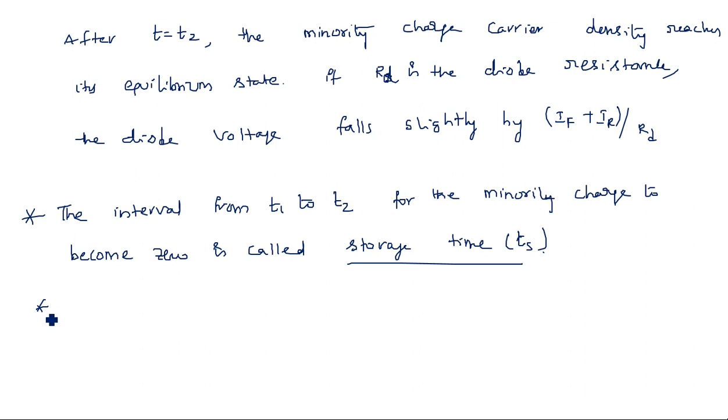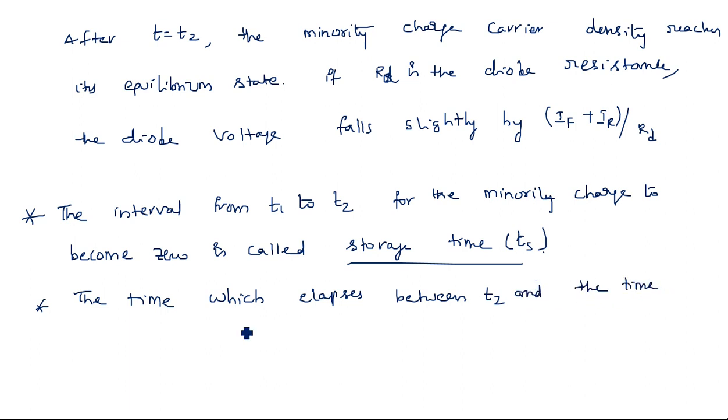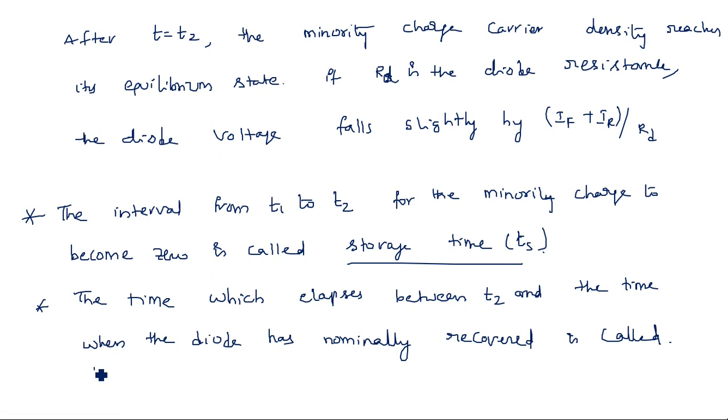And what is the other one? Transition time. The time which elapses between T2 and the time when the diode has nominally recovered is called the transition time, TT.